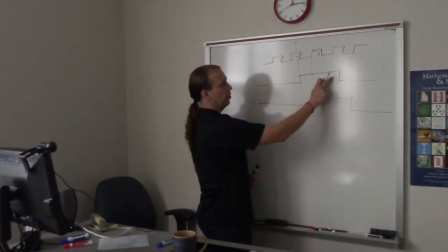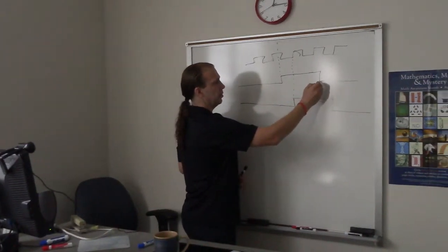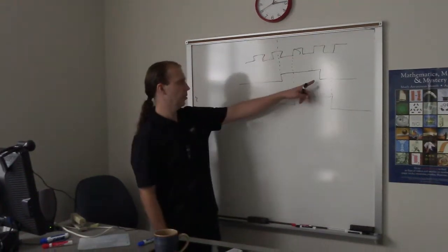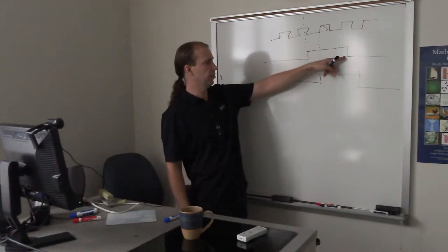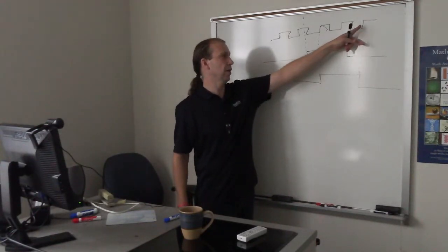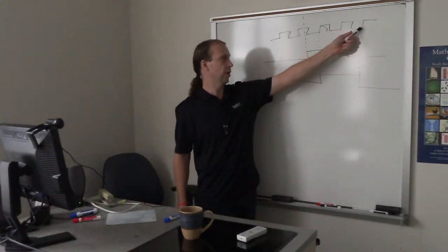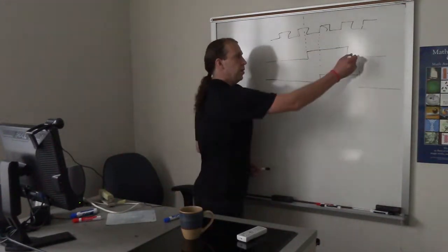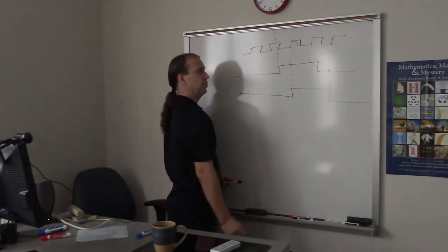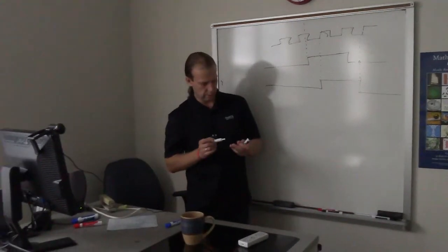It was high, and then it went down, but this change of the signal level is not going to affect the state of the finite state machine unless we see the next rising edge of the clock cycle. And only when the rising edge of the clock cycle is seen, we're going to make the transition. Actually, we want to read the value of the input signal, and we want to copy it to the output.